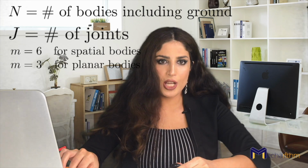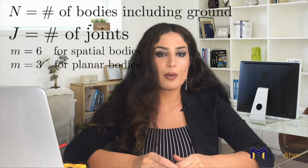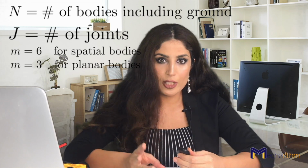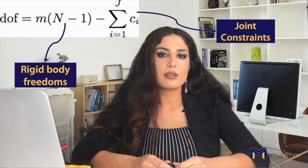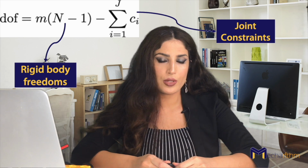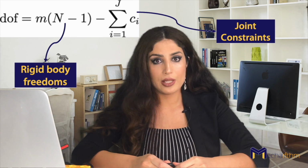And if j is the number of the joints, and if m is the number of degrees of freedom of a single body, that is 6 for the spatial bodies and 3 for the planar bodies, we can write the degrees of freedom equal to the freedom of the bodies minus the number of the constraints. Note that we deduct 1 from the n because we want to exclude the ground.